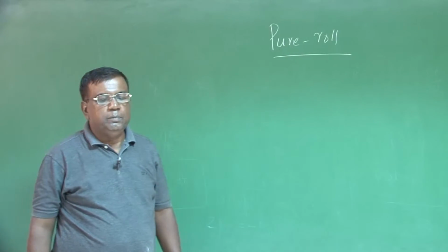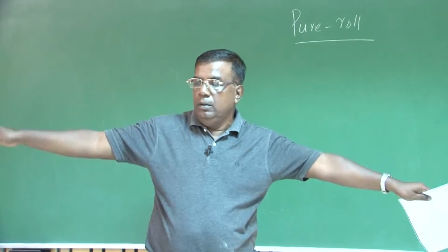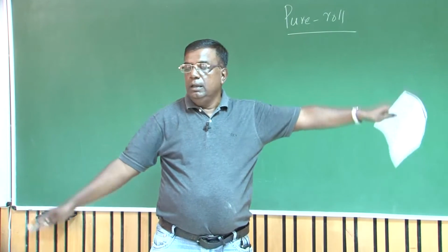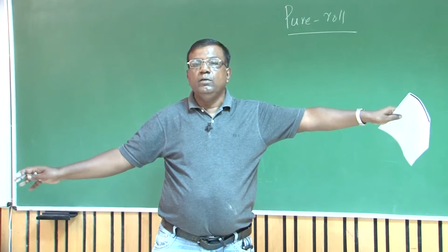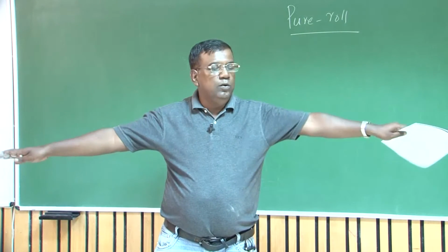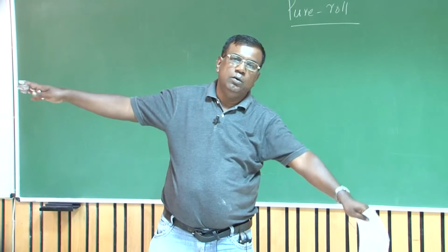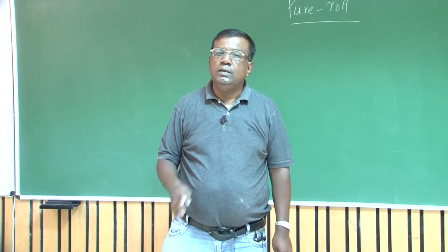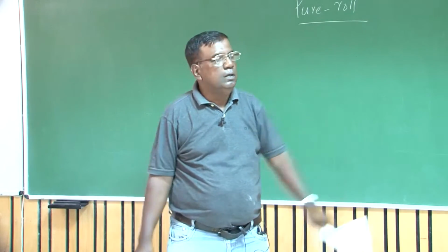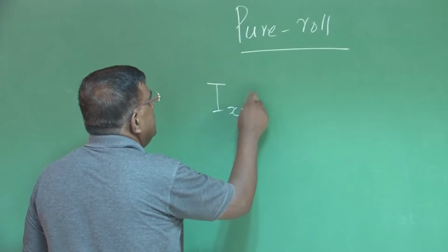Before we discuss this, please understand that by pure roll we mean this is the pure roll. But as I roll like this, the angle of attack here will increase, so drag will also increase here. That will give me a yawing moment also. Like when you are doing yawing motion, the lift here will increase, and it will give a roll also. But we are seeing only one dimensional motion, that is, we are only talking about pure roll, no yaw motion.